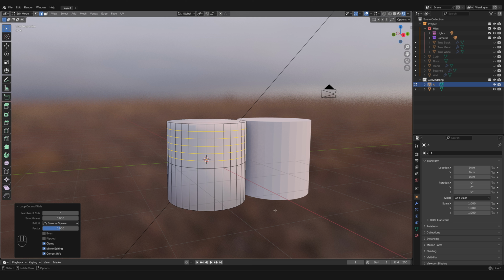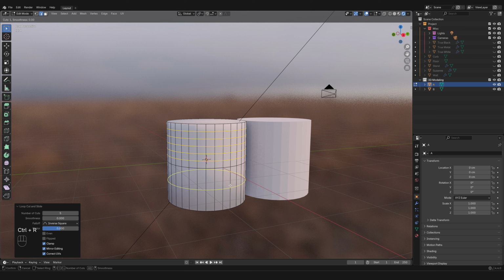At the same time, when you press Ctrl+R, right at this moment, you could type 5, and you will be previewing the same thing. Now you can bring in 5 edge loops at the time. And if you change your mind, backspace to cancel, and all of these numbers are showing up here in the top left corner where you have the manual input information.